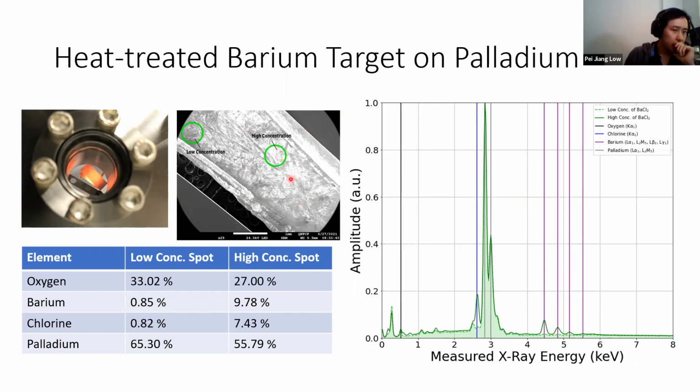These white parts over here are the parts with the salt. And you can see some scratch marks over here as well. These scratch marks are our attempt at seeing if it flakes off easily after heat treating it. And from what we have seen, it does not flake off easily, and you can see these marks over here because it is bending the metal as we scratch it.